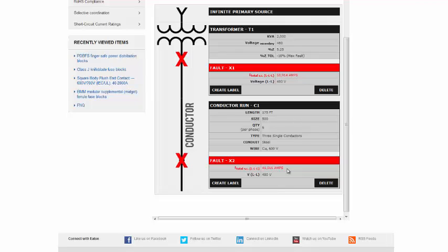So the National Electrical Code provides for the fact that you have to have a correct and proper short circuit current rating on your equipment. And this is a way to find out how much short circuit current you have so that you know how you need to build that or how you need to specify it.